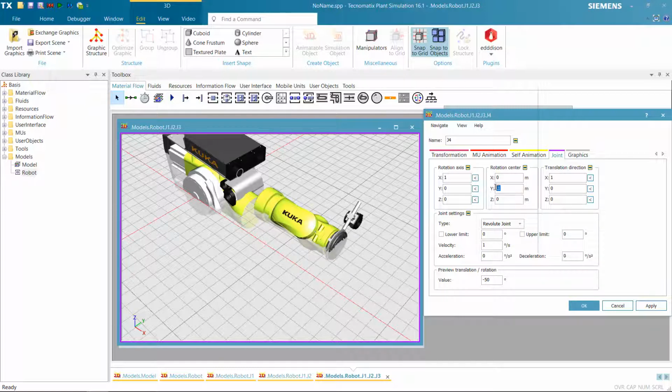So for that reason, for this tutorial, I will just keep to 3 joints. And for joint number 4, if you are very interested in doing more joints, you will need to be careful on how to find the rotation centers, or you can try to restructure your hierarchies to make them stronger hierarchies before sending into Plant Simulation.